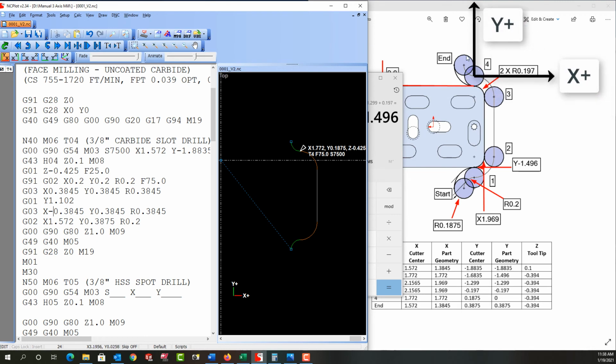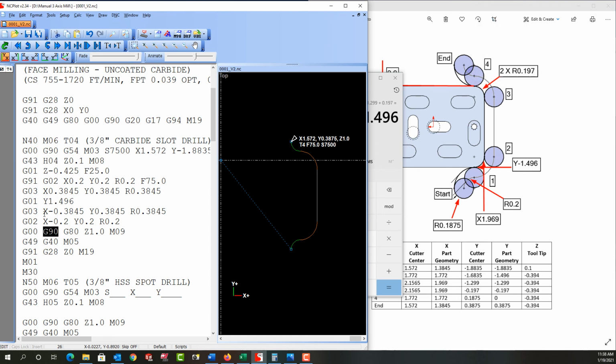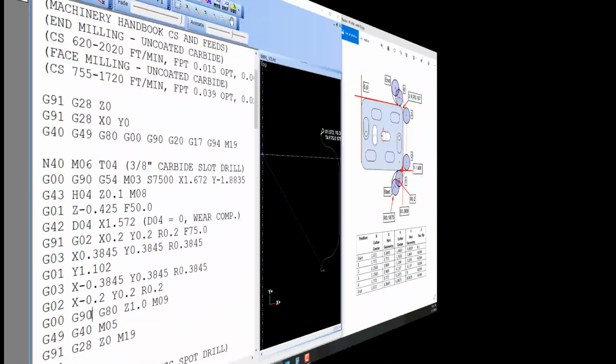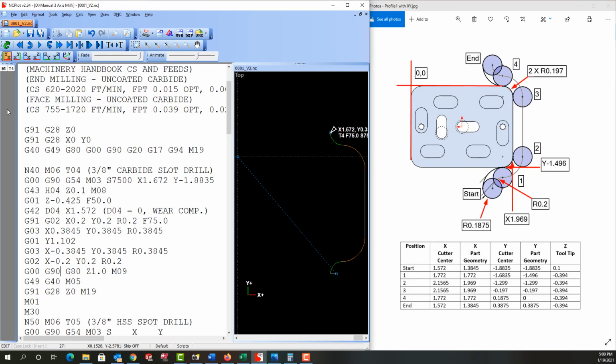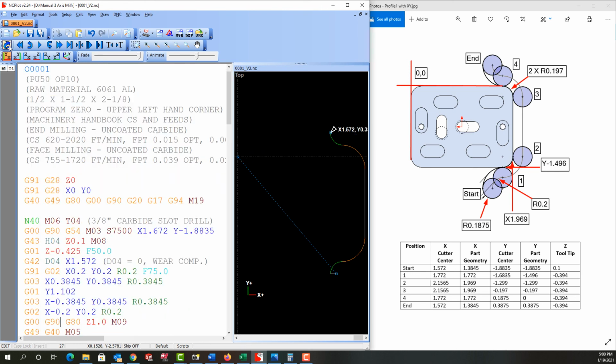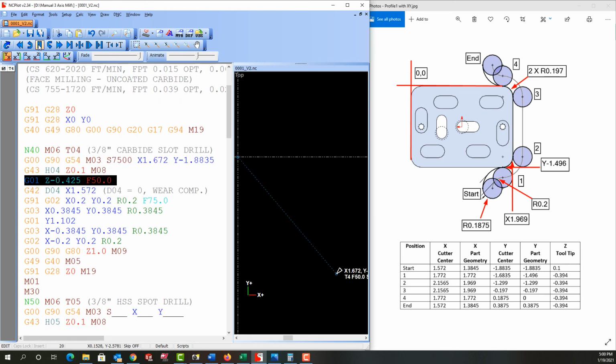And our last incremental move, once again, we'll put our Cartesian coordinates here. Cutter's in quadrant 3, so it's going to be an x negative, y positive, this radius, which is 0.2. So once again, I'm going to copy and paste this, then add the negative sign. And I've now switched this to incremental programming. That's why earlier I suggested we always put a G90 here, because we often switch between absolute and incremental. Let's just refresh our plot, and then I'll play it. So once again, the cut is fine, and we could program it in absolute coordinates or in incremental as we've just done now.